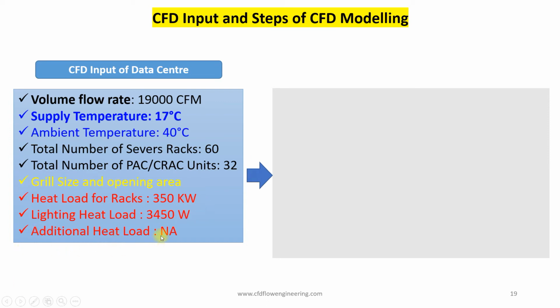Among all heat loads, the heat load for the rack is high. It is on the order of 300-400 kilowatt, depending on how many servers you have placed in a rack, and that heat load is distributed among the servers, and that heat is absorbed by air.